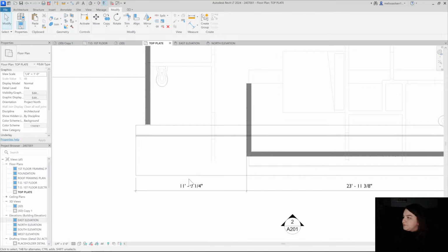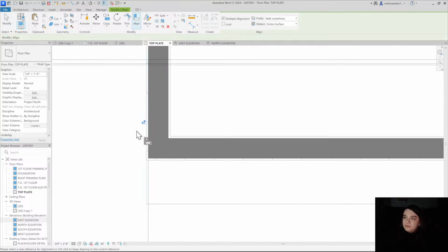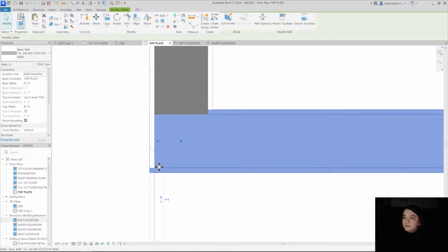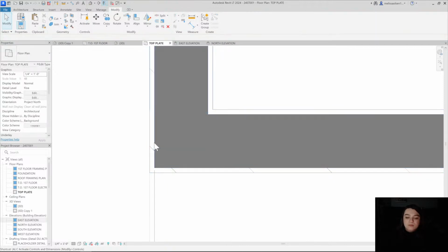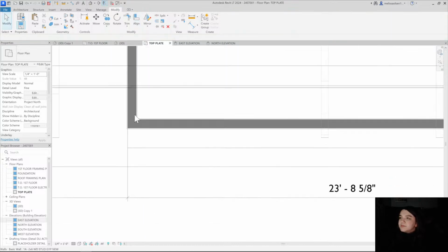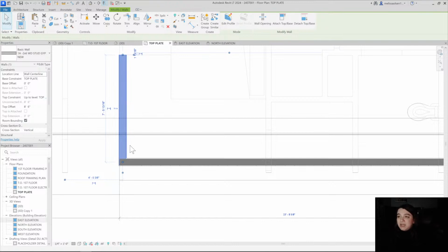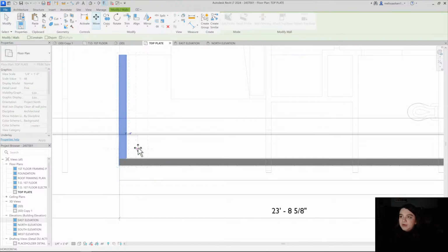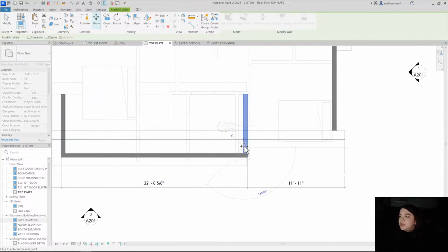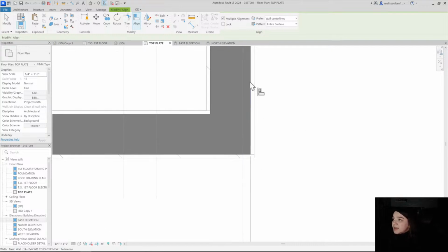Okay. So I definitely want the stud to align with the edge of it, and then from there it's a 1 foot offset. I'm always measuring from studs or wooden points, never from a gyp or exterior point. I'm going to move that in once it's aligned to the edge.